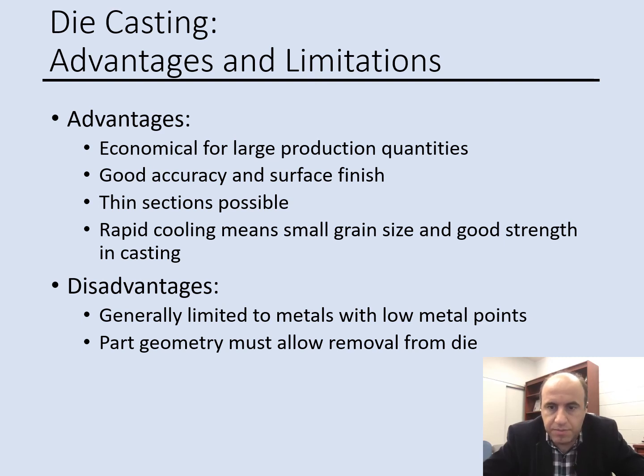And the limitation is that it is limited to low melting point material, and you need to consider some simple geometry because we want to remove the part from the die, so the part cannot have a complex geometry.